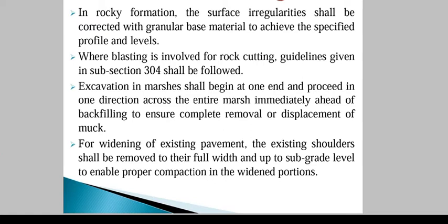So overall, the quantity of cutting and the quantity of filling for the selected stretches should be nearly equal, so that we can use the cut earthen material as filling material, as an embankment, which will reduce your cost. And in the cutting portion, the side slopes need to be taken care of. Steep cutting and higher depth of cutting should be avoided. So thank you very much.